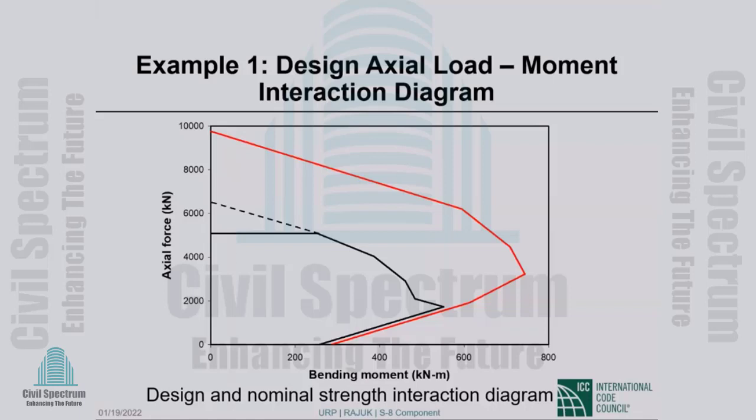I do not know a direct answer, but a column is under compression almost always. If a column has cracked, there is a problem. So it has been subject to tension for some reason. I would rather figure out what happened than try to figure out the capacity that may remain. Spalling indicates high compression. Rusting also leads to spalling.